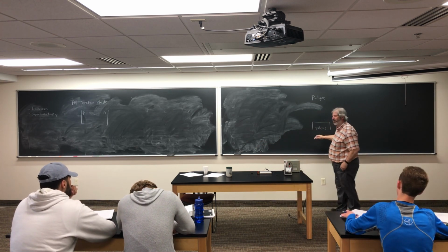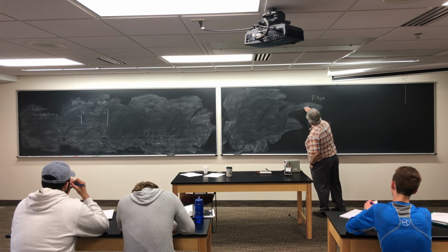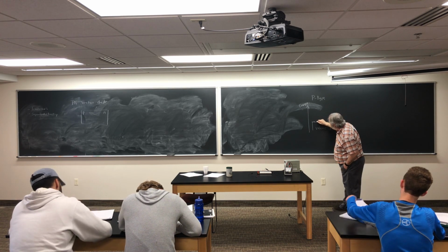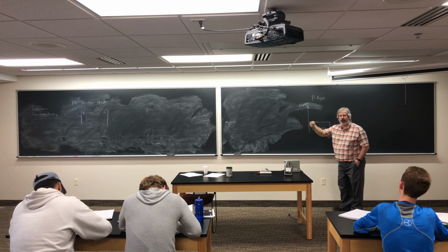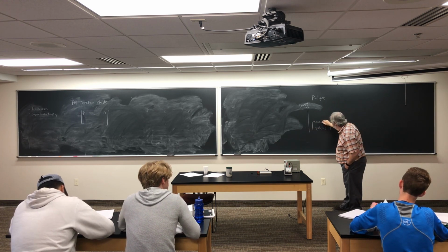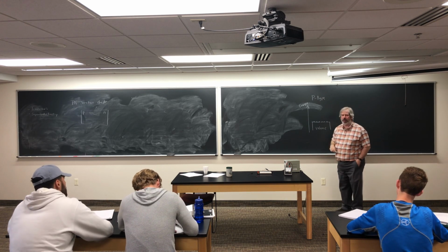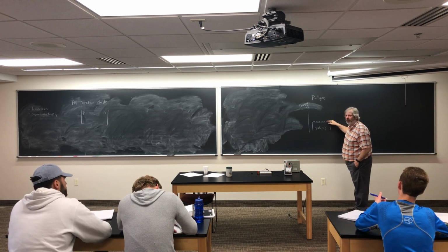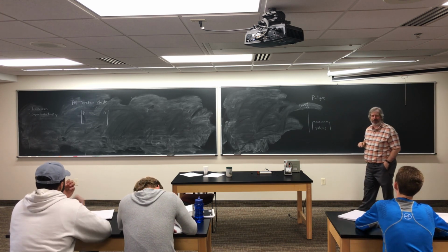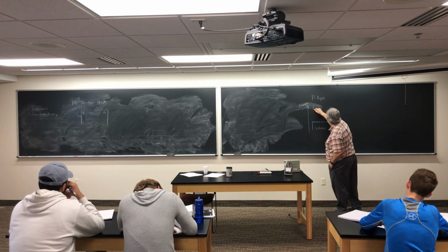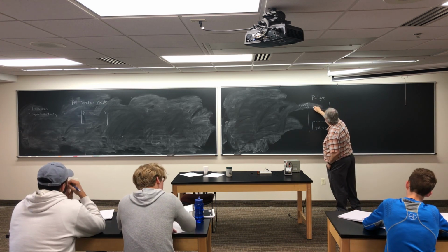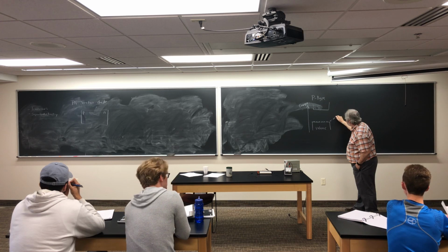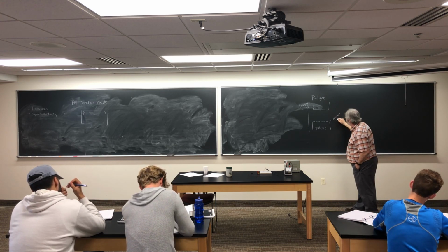So as far as energy, you're creating places because the electrons don't need much energy to go fill these holes. So you're creating little energy levels right above the valence band. So when an electron fills a hole, there's a little bit of energy there to do that. Okay? So we call those acceptor levels. I don't think I said that. They'll accept an electron.